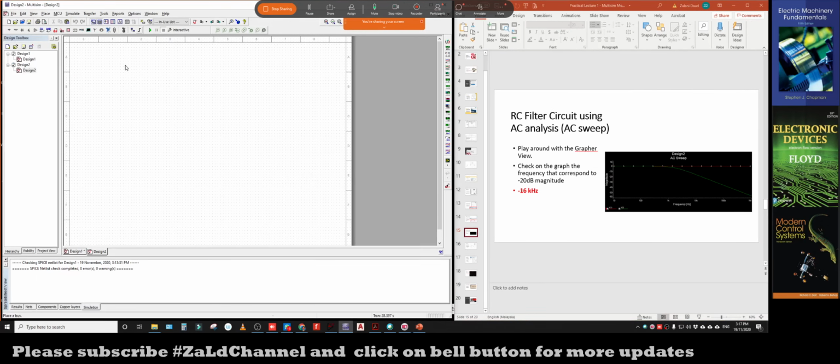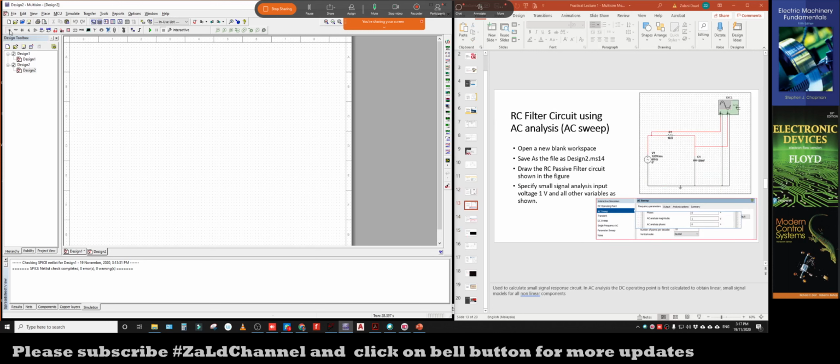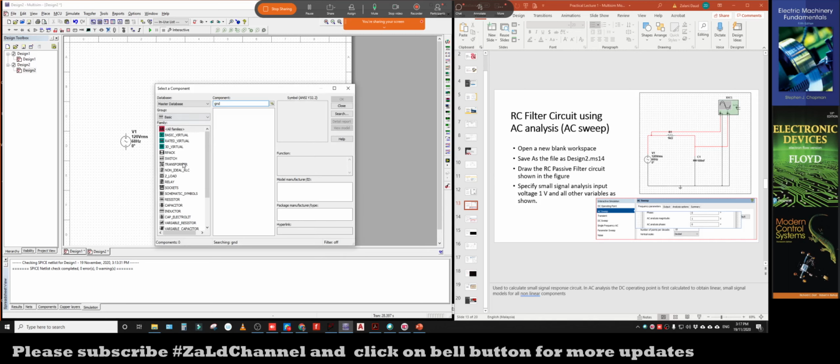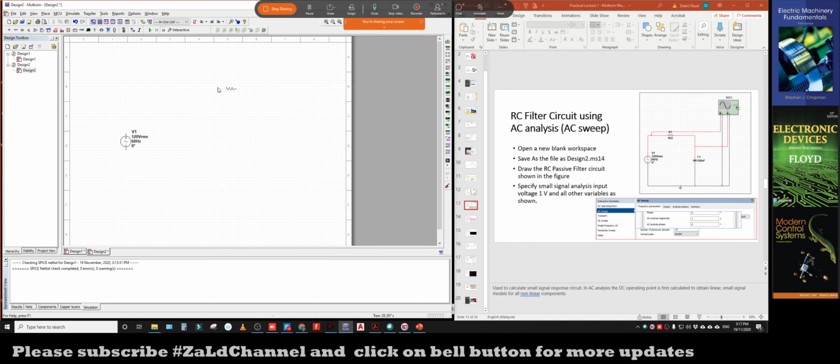Let me show you one by one. Basically we want to place the source, so I click on source. Now I'm going to place the AC power source, not DC. Click on AC power source and place that source. Next we're going to place the resistor. Find the resistor in basic components. What is the value? 1 kilo ohm, which is 1k by default. Put the 1k resistor.